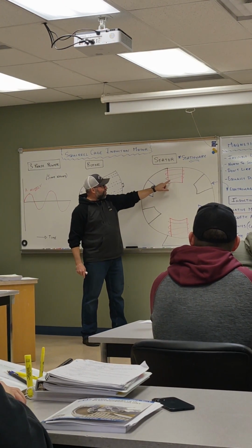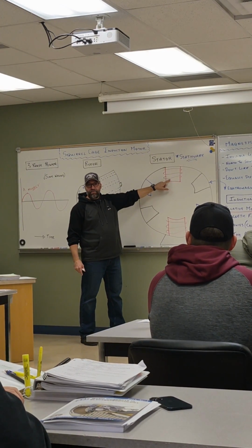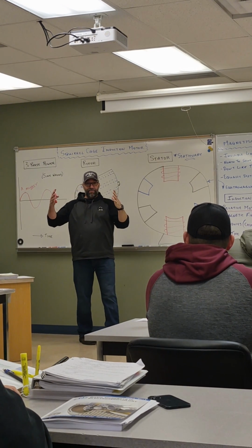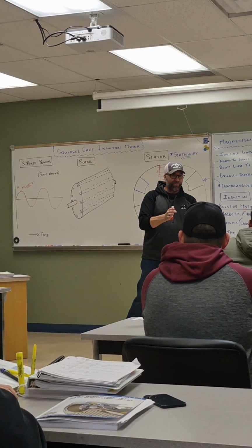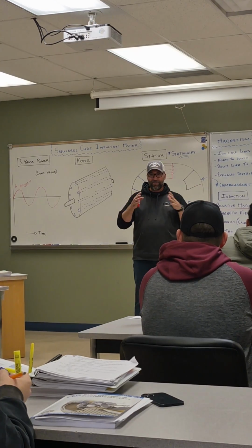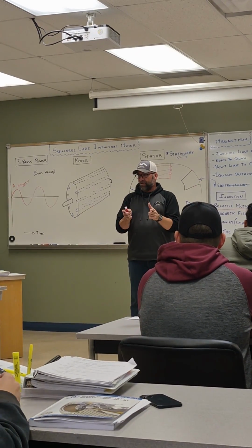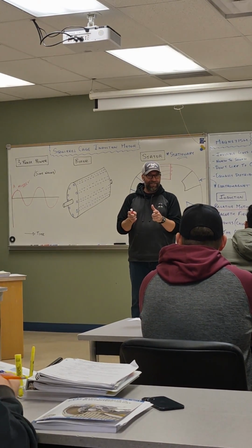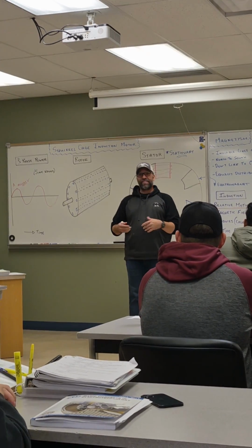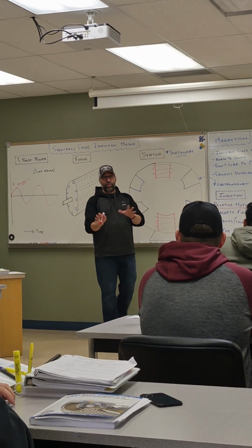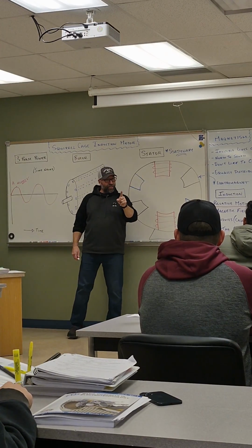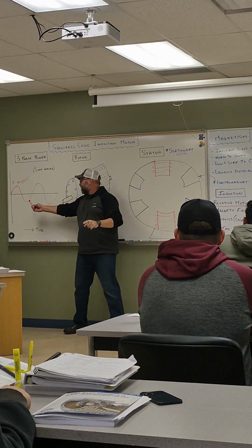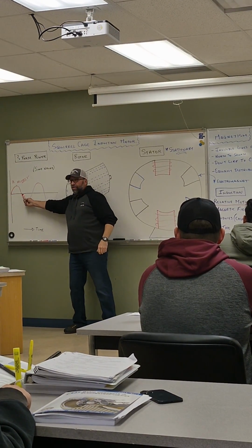The whole reason we wrap it on a pole, an iron pole, is because that magnetic field, just like current, takes the path of least resistance. It will all concentrate into that iron and turn it into a magnet. Different word, it's path of least reluctance when we talk magnetism, but don't worry about that. I just turned that into an electromagnet, and I turned it into an electromagnet that only operates when this voltage is above 0.